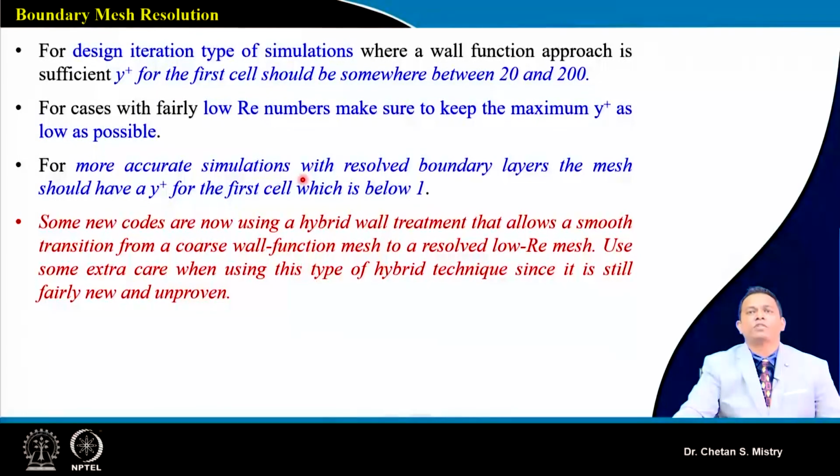There are some commercial calculators available, in which you can put your Reynolds number as one of the parameters along with some flow properties. It will give you the calculation of y plus. That y plus value we will be using for making the layers near the blade surface.